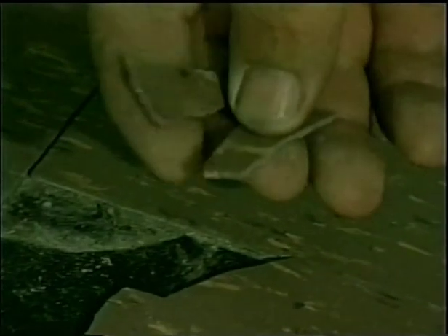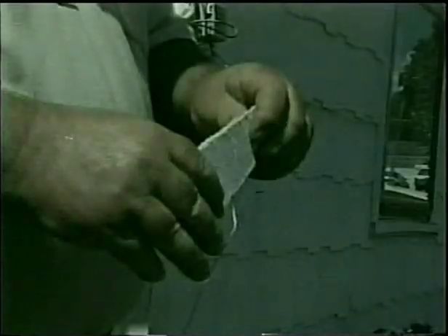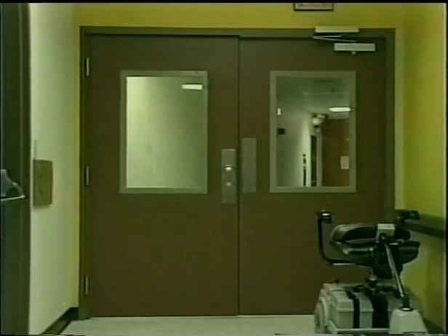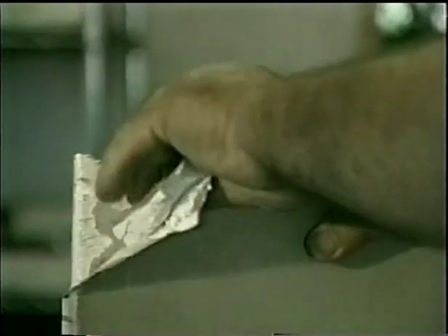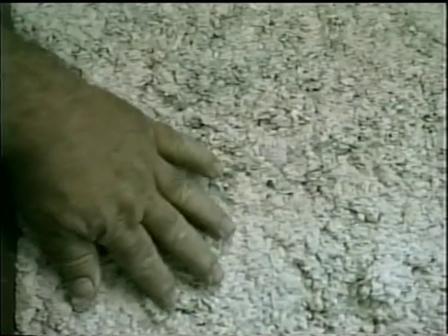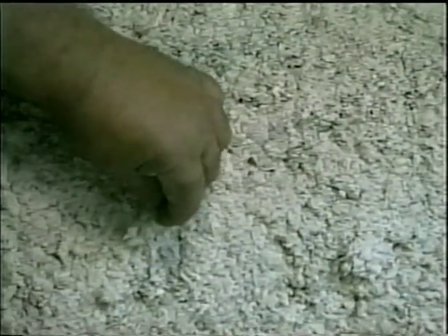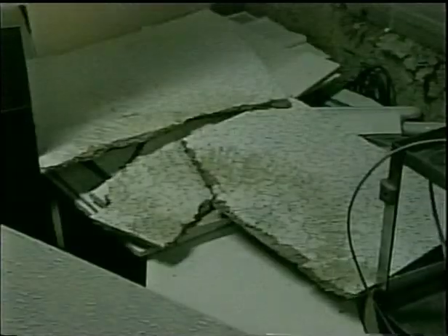Other building systems that may have asbestos in them include ceiling tiles, floor tiles, laboratory cabinet tops, shingles, fire doors, siding shingles, drywall, and hard plaster. While some of these materials are considered friable, they are all examples of materials that will not release asbestos fibers unless they're disturbed or damaged in some way. If an asbestos ceiling tile is drilled or broken, for example, it may release fibers into the air. If it is left alone and not disturbed, it will not.